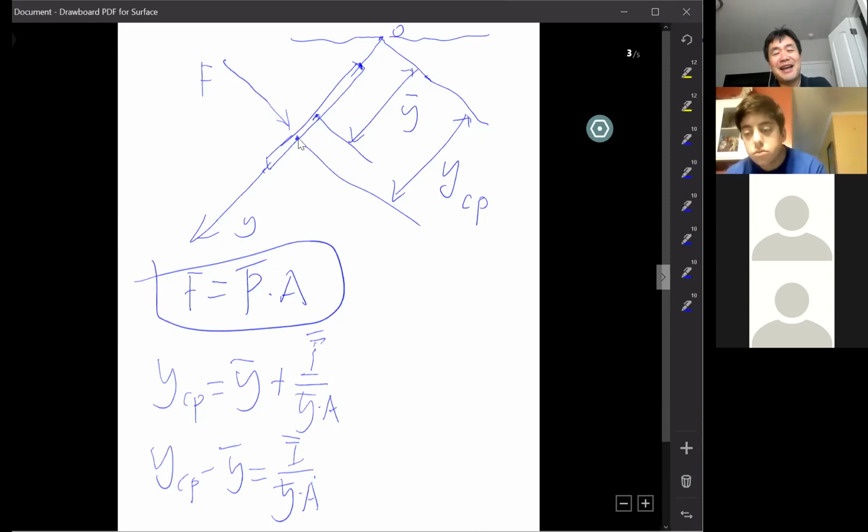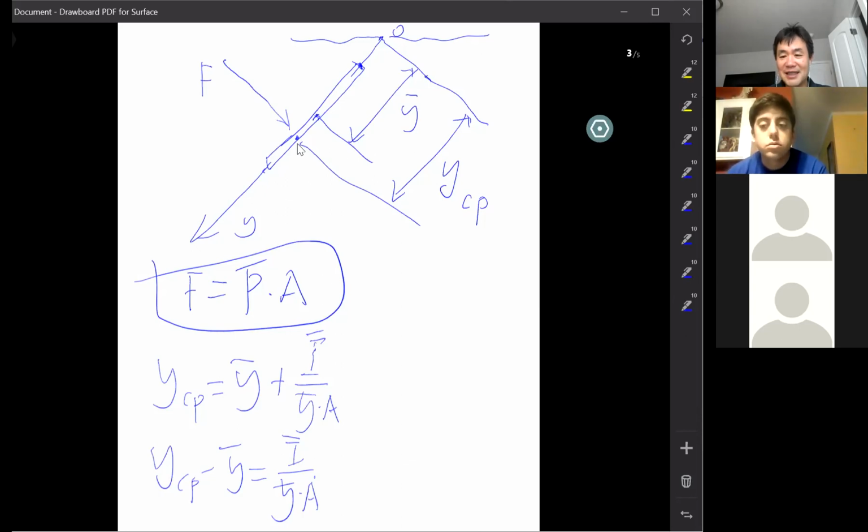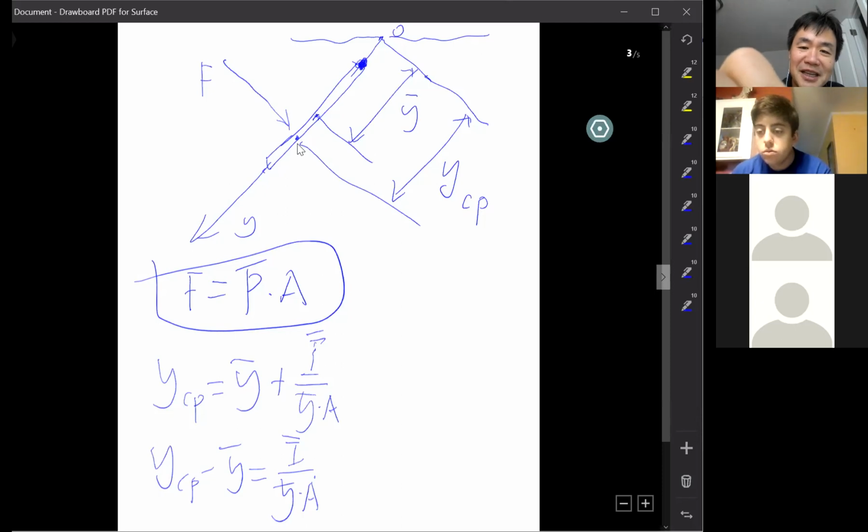So you may ask why I need to know the location and point an arrow to it. Don't forget, for the rotating problem, you need the calculation of moment instead of just the force balance. How do you calculate the moment? For example, I put a hinge on top of this plate. This plate is going to rotate about this pivot point, this hinge.